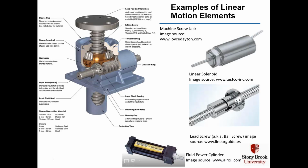Here's some examples of linear motion elements. The simplest one is a linear solenoid. You give the solenoid a voltage and this little pin moves in and out. Here is a lead screw that we'll cover in this chapter, in which you rotate the screw and this nut translates up and down on the lead screw depending on which direction the screw rotates.